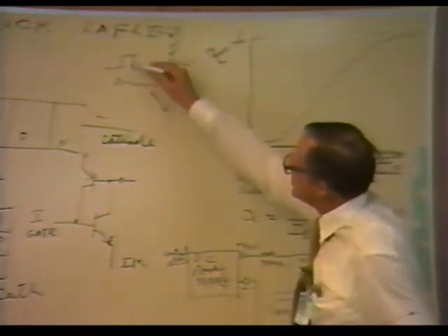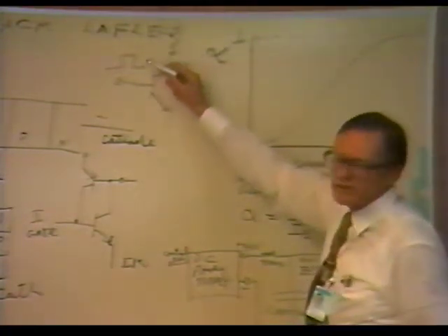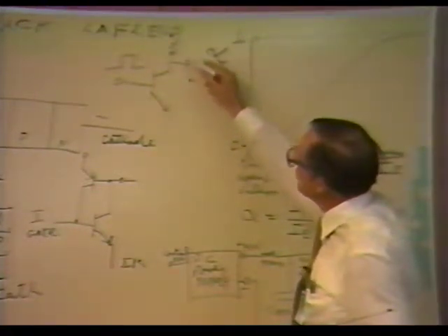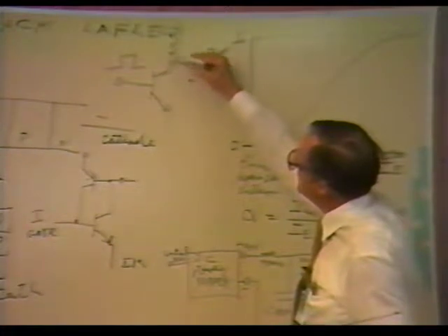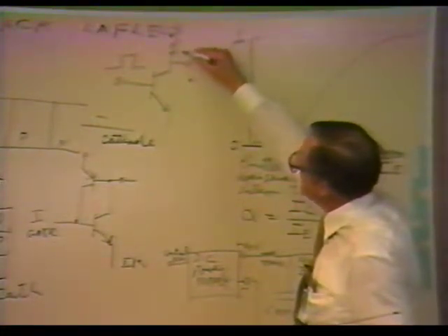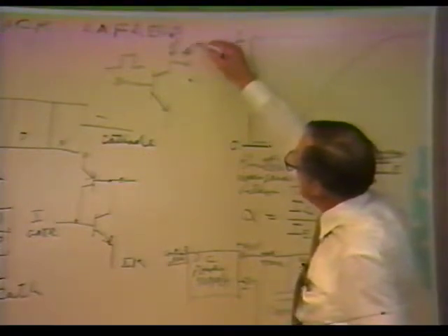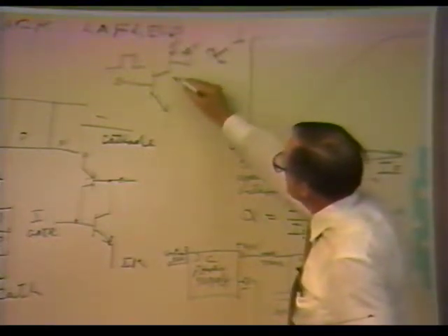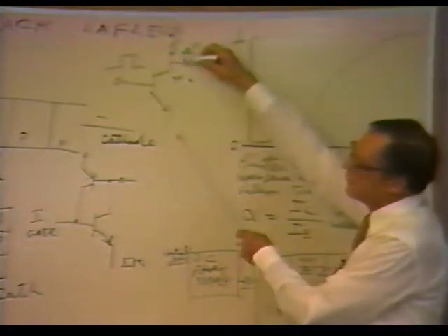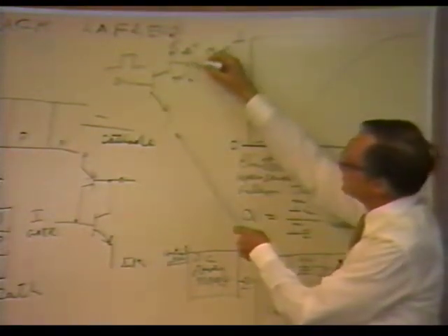Okay, I am turning this transistor on as hard as I can turn it on. I'm putting it in saturation. So the voltage goes from whatever the collector voltage was there, and let's say it was 30 volts. When nothing is conducting and I go across here with a voltmeter, I'm looking at 30 volts.